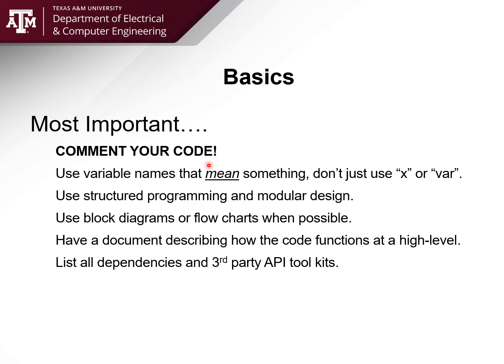Use what we call self-documenting code or self-commenting code, and that's using things like variable names that actually mean something. If you've got a temperature sensor, don't use the variable X or var. And you would think that this is a joke. I have actually come behind firmware that uses X and var as variable names, like X for the pressure sensor on a casing pressure. Well, that doesn't tell me anything. I don't know what X is.